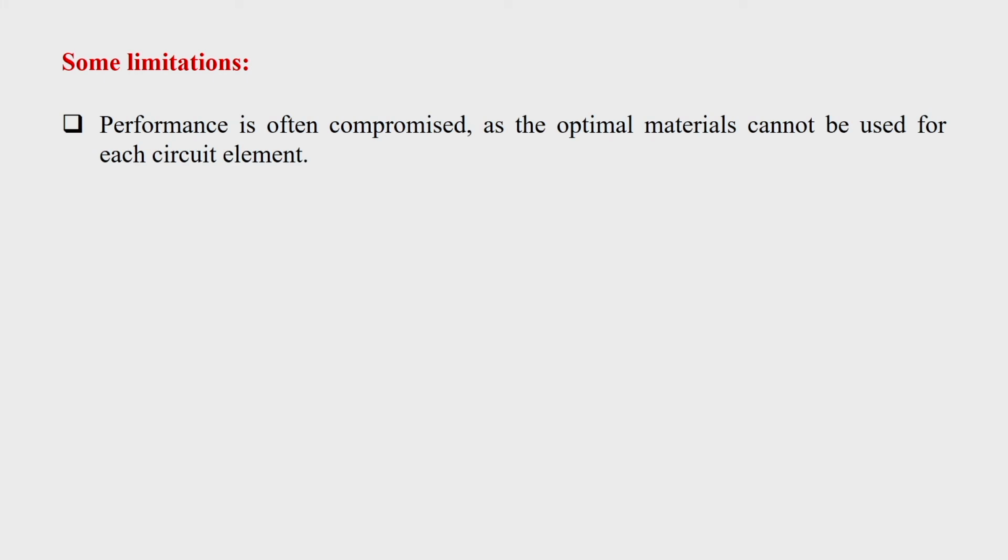However, MMIC technology also has some limitations. Performance is often compromised as the optimal materials cannot be used for each circuit element. So, we had that flexibility in hybrid MIC when the material for individual components could be chosen, but here we do not have this flexibility. Power capability is limited. This type of MMIC can handle a limited amount of power.